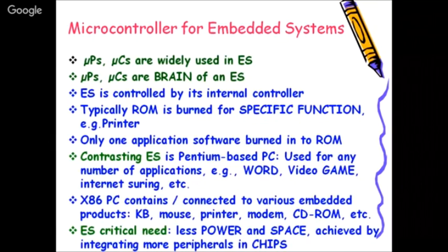Each of these individual peripherals, like your keyboard and mouse, are input-output peripherals. These are embedded systems in themselves. There is a controller which resides inside. For example, in the case of a mouse, there is a PIC, a small tiny 8-pin controller chip, which resides inside the mouse and receives commands from the CPU about the particular location of my pointer. So this connectivity is there.